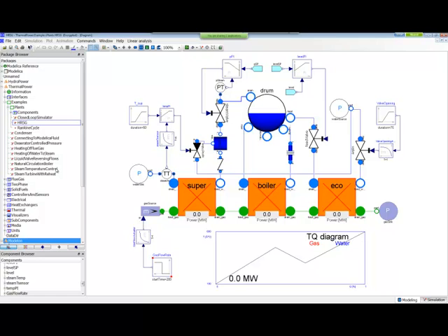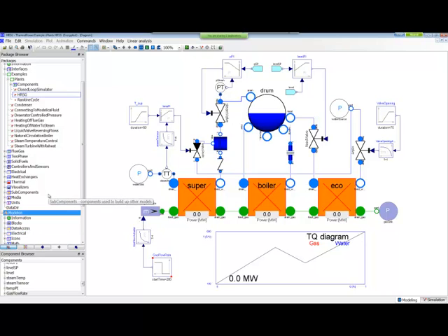I can say that the main reason we chose to do a new media structure is that this thermal power library is based on the Modelon base library, so we want to have one common library with the same structure. When it comes to performance, with our new water media model it should be possible to get analytic Jacobians, which is not the case if you use the Modelica standard library.